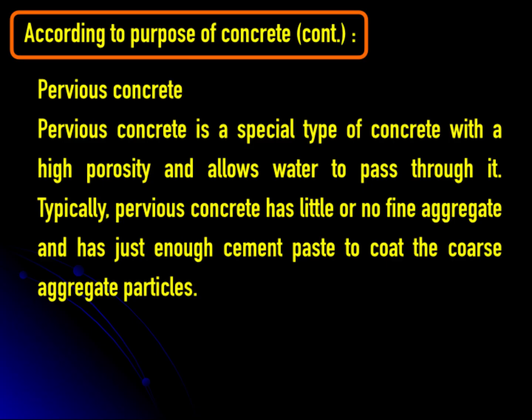Pervious concrete or porous concrete, also called no-fines concrete. It has high porosity or large voids, allowing water to flow through the concrete. This concrete typically contains no fine aggregate. This type is useful in parking lots, urban lawns, and pedestrian walkways to reduce runoff from stormwater.